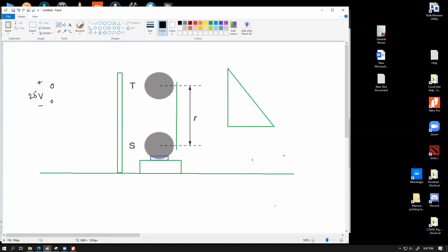So if it's a 20 volt supply, and then you have a switch, you have a variable resistor to change the output voltage, and let's say the negative end is connected to the ground, you can essentially use this point to have the voltage connected over here. But how would you measure this voltage? You can think about connecting a voltmeter across these two ends. Whenever we have connected the negative end with the ground, this end will become 0 volt, and this positive end will become plus 20 volt. So this perfectly serves our purpose.